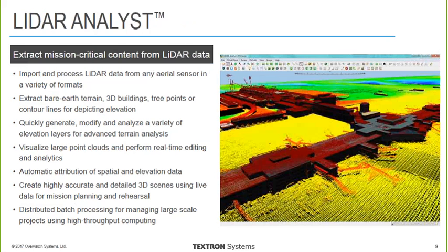That's the beauty of the tool. We're able to quickly go in, visualize as a DSM, build a DTM, hill shade them, extract buildings, trees, vegetation, different types of topographic products, contour lines, and so forth, all more or less with the click of a button. So we're able to really get in and dig into the LiDAR data quickly.